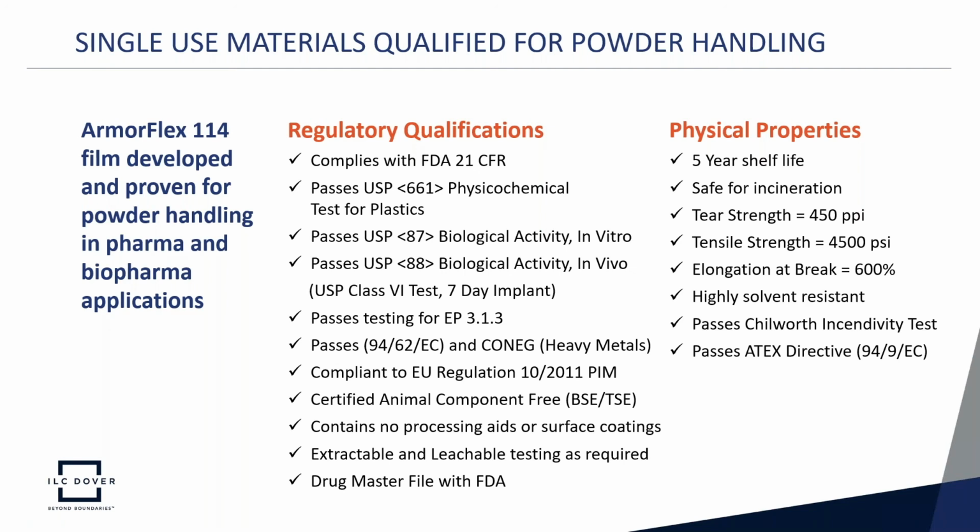So you can see we have very high tear strength, high tensile strength, very strong elongation at breakpoint. And then lastly, we have the unique part of the powder transfer bags, which is to meet the required static dissipative directives that are out there, the Chilworth incentivity, and for Europe, the ATEX directive, in meeting the surface resistivity required for the ATEX directive.